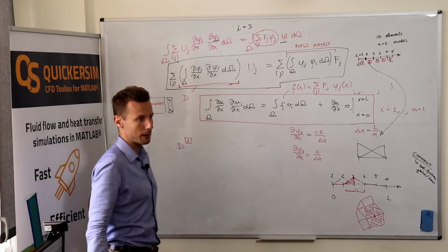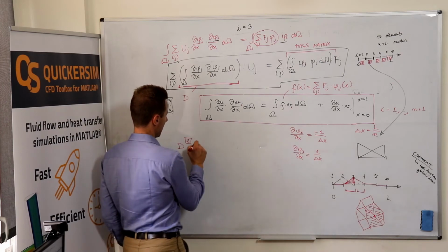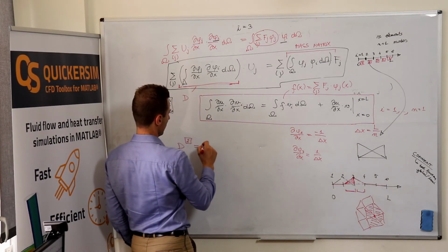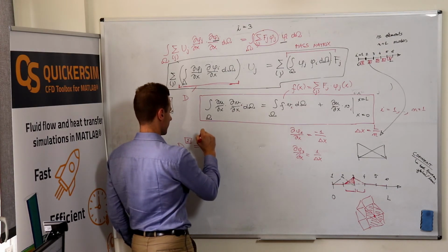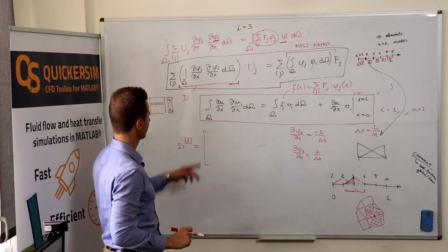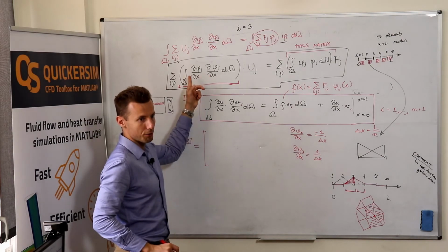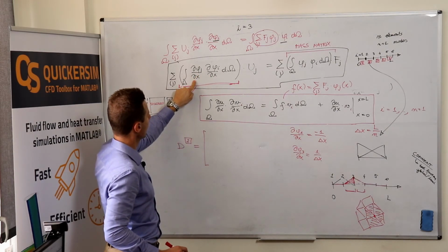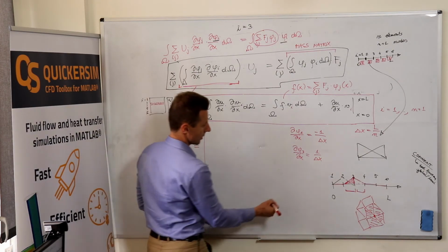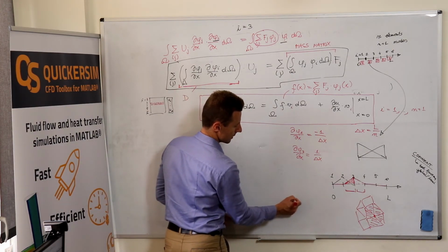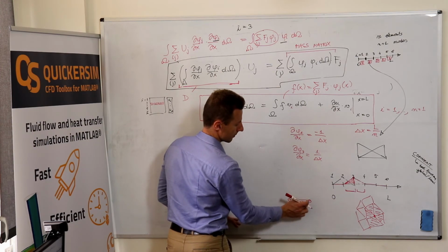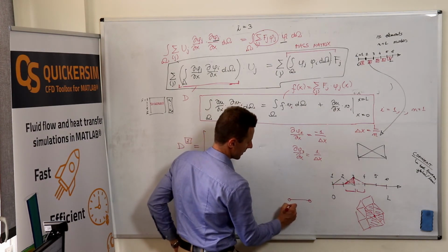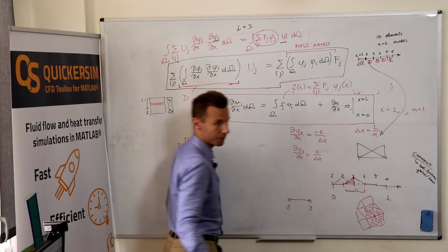This will be the diffusion matrix for the second element. Well, and let's use this formula to compute it. Luckily, all the terms are constant. So what do we need to do? First, we define the local element. The local element has got the second node and third node.